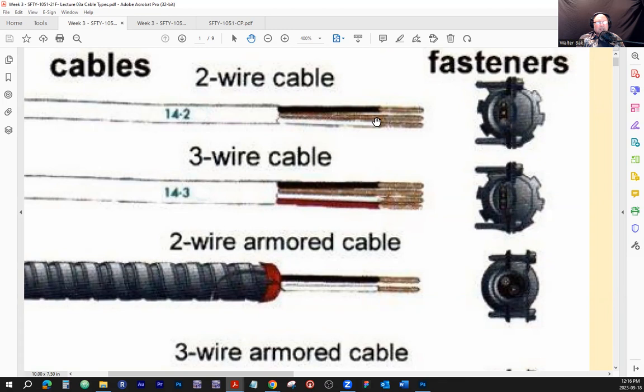It doesn't go through any other connectors. If the terminal hits another connector first and then is joined to the ground, then technically it is grounded, but in the industry we call it bonded. All right, so you're going to hear me using the grounding and bonding terminology interchangeably, okay?